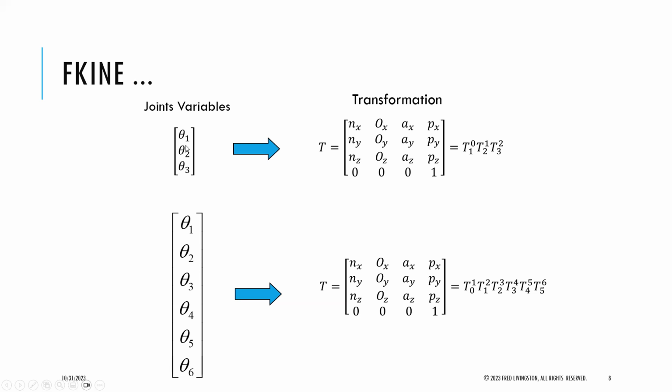So we're assuming this is rotation, rotation, rotation, a 3R robot, and it has a 4x4 matrix here. And we're assuming this is a 6 degree of freedom robot, all R's, so all rotation joints. Or this would be a Q for prismatic joints here, and this is still a 4x4 matrix. And you're doing the chain rule: we just do the transformation with all the things inside of that and have a single transformation.